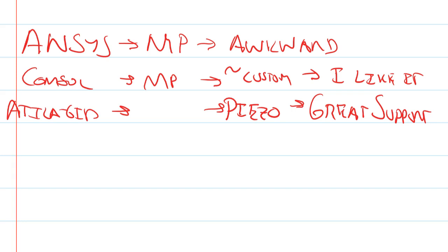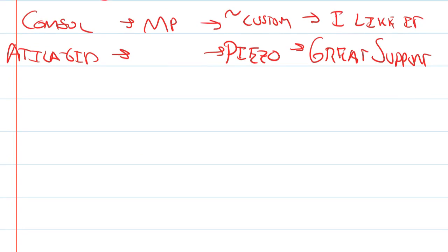And remember, with simulations, you want to go as simple as possible. You don't want to make things as complicated as possible. So despite some of the limited factors in multiphysics, you may say that you have your piezoelectric device interacting with the fluid and you want to model all of that. Well, in my opinion at this point, it's not very likely you'll get a lot of benefit from hooking those two things together. You could still use Comsol or something else for a CFD, which you might already have, but hooking them together, it's going to be tough to get results that mean anything, or that you can actually interpret to the extent that you simulated it. And it's going to cause a lot of computing issues too with how much memory it takes.